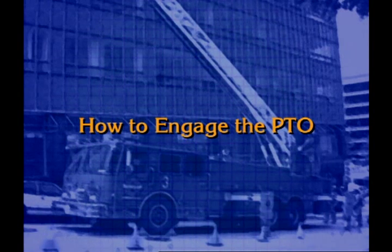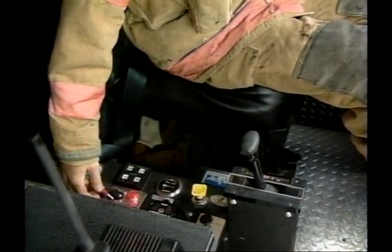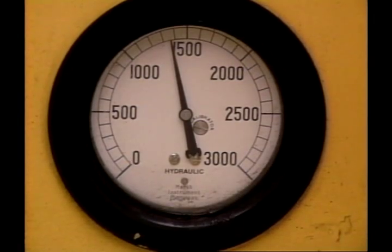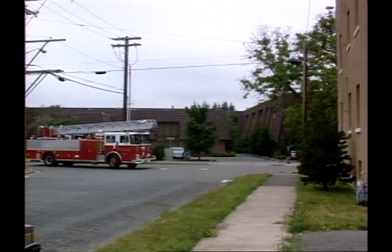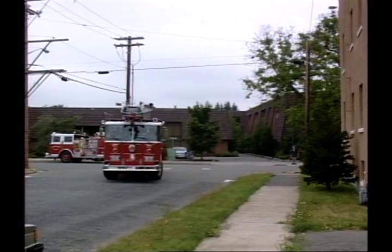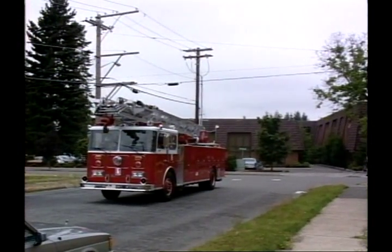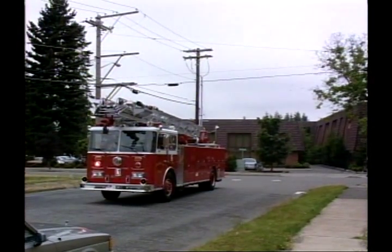Power for the hydraulic system is provided by the power takeoff or PTO system. Engaging the PTO provides power to the hydraulic pump, which then creates pressure on the oil in the system. The process of engaging the PTO is similar in most apparatus, but there are a few differences. Let's look at engaging the PTO in different types of apparatus.